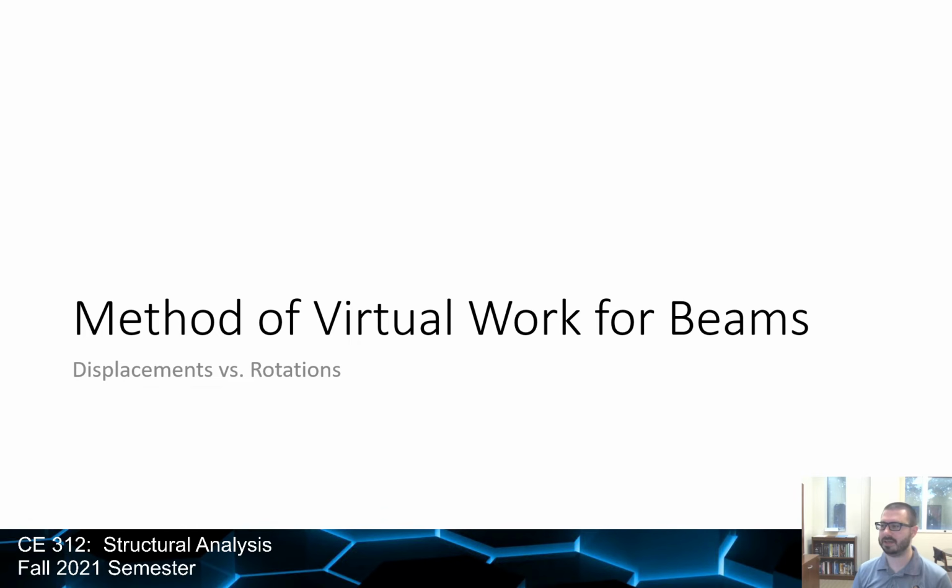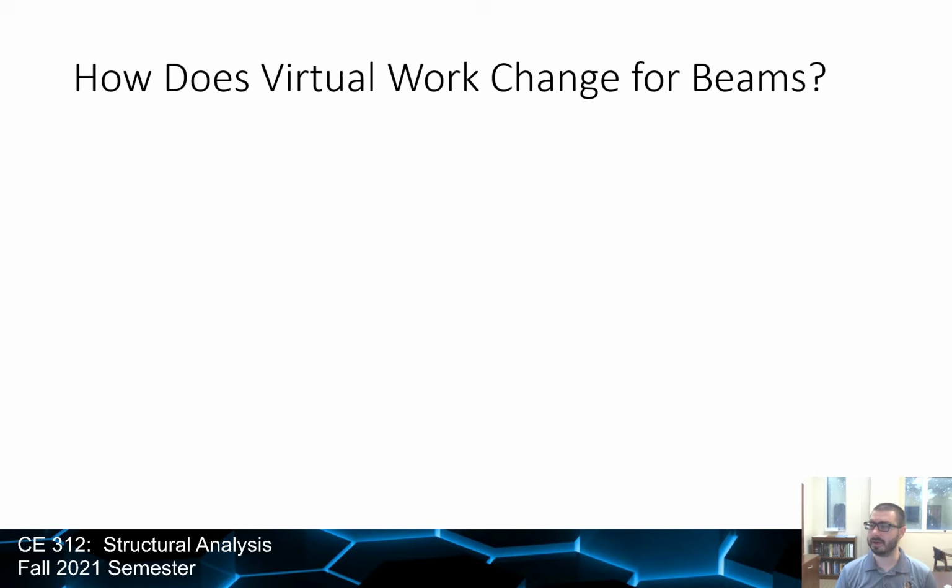But the reason I like to use virtual work is that we can use the same concept and approach that we used for trusses, the real load and the virtual load, and then plug it into a simple to remember expression. That same approach will work for any beam subjected to any loading. It also, and this will become clear near the end of our discussion of deflections, is a lot easier to assess the deformations due to other types of mechanics, such as shear deformations or axial deformations and so forth. So we're going to use virtual work.